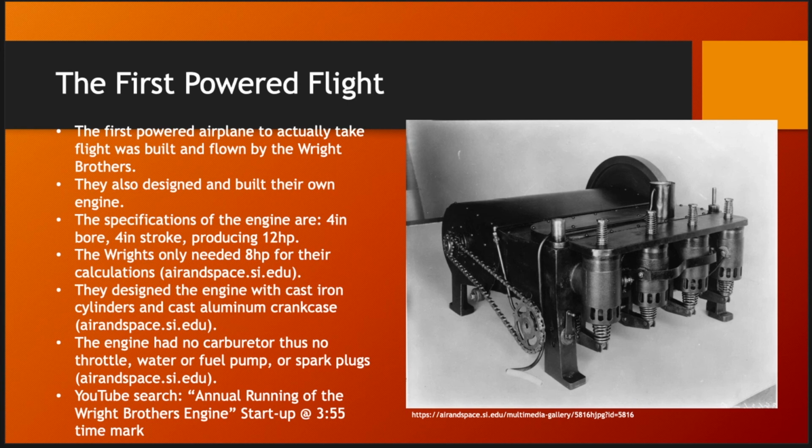But instead of circulating the water, there was a hole on the other side of the engine, so as the water went in, it evaporated. Evaporation can also cause a little bit of cooling, but not that much. It's a really inefficient way to cool an engine, obviously. And then it obviously didn't need a fuel pump because it just used gravity feed.